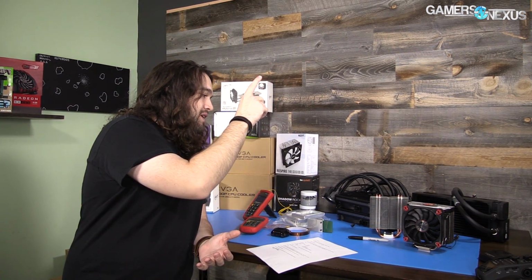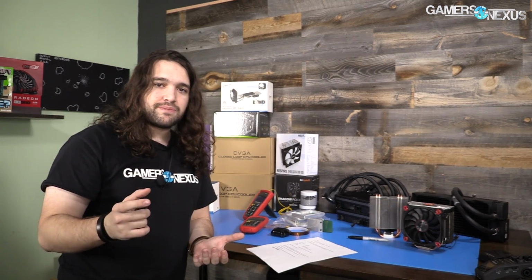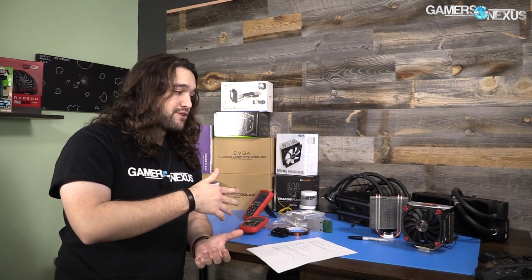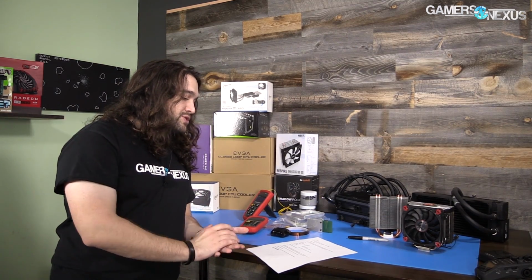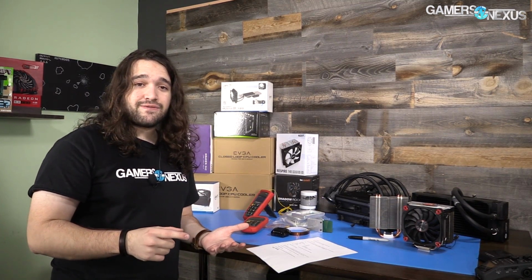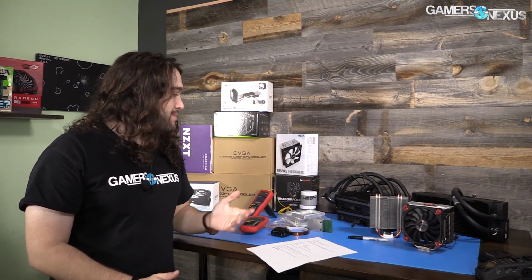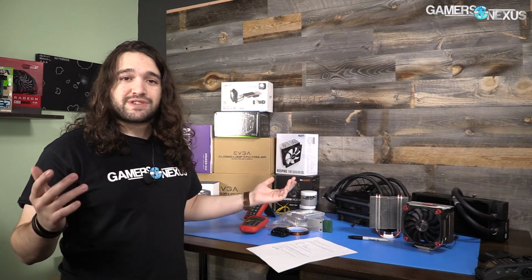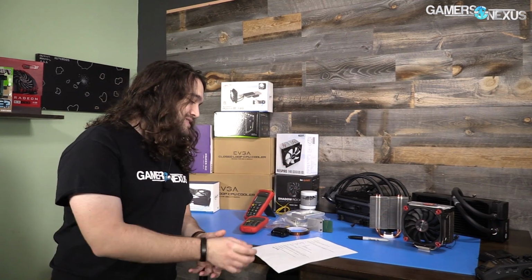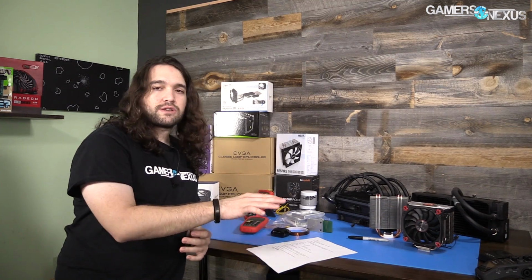whether it's air or liquid. That's because the temperature that is ultimately being pulled through the radiator is going to be the ambient temperature. So it's impossible. If you see temperatures that, when you produce a delta value, are negative, that means something went horribly wrong. It could be a negative 0.5, and that might be a calibration thing, or it could be negative 5 or negative 10, and that's wrong. It's not possible.